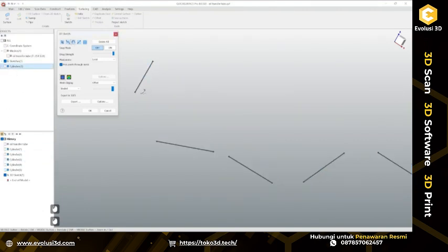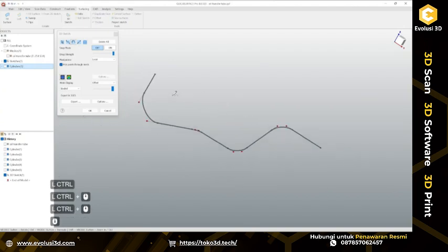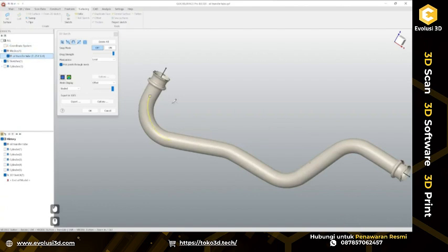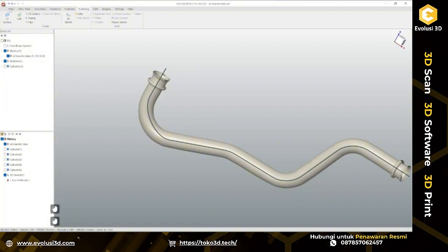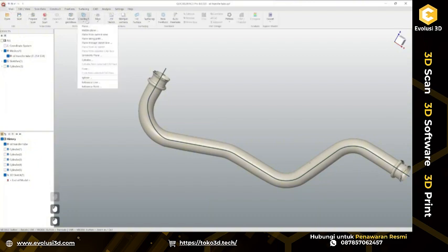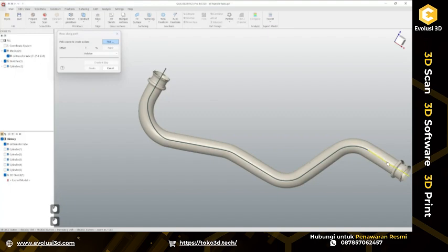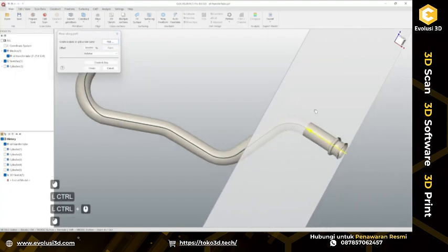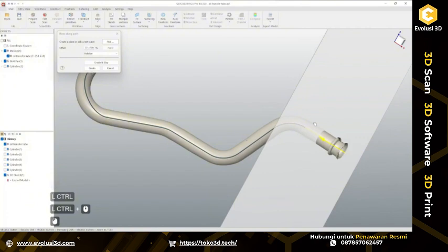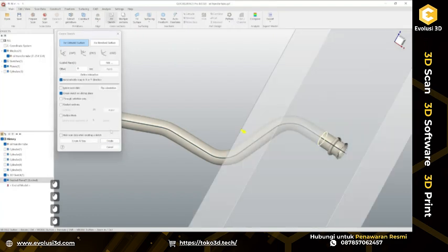And after that I'm going to use the simple blend tool to connect all of them into one path. Okay, like this. Of course we will need to do some adjustments here, but for now simple blends will work good enough. And at this point I want to construct a plane along the path, let's say probably along this entity here, somewhere where I can see a straight section of this pipe. Okay, let's create a sketch.